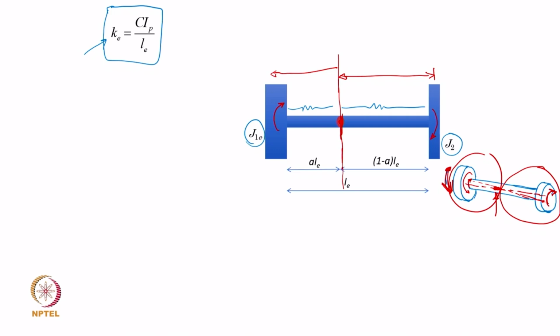These are all the conceptual discussion of how they will oscillate or vibrate, but it is sure that when they vibrate at the second natural frequency, there is going to be a location along the length of the shaft where the twist will be 0 and the left hand side disc will move in a direction opposite to the direction in which the right hand side disc oscillates.